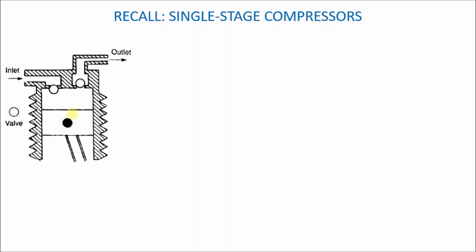And when it does that, of course, the volume of the air inside of the cylinder will increase slightly. And after that small expansion phase, then again the outlet valve is going to close and the inlet valve will again open and the piston will continue to move down, and that will be again the suction phase that will begin, and the cycle will repeat itself like that continuously.